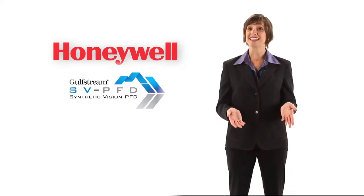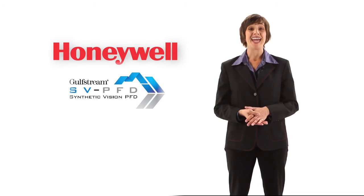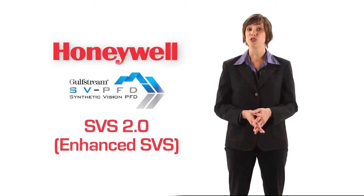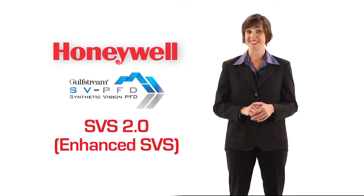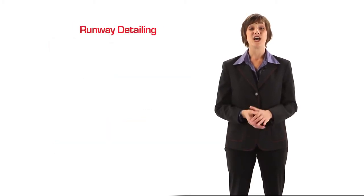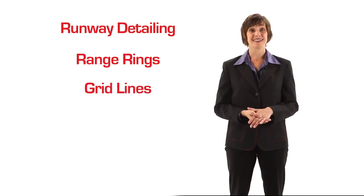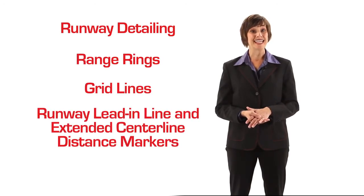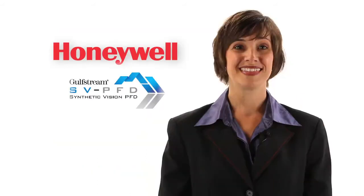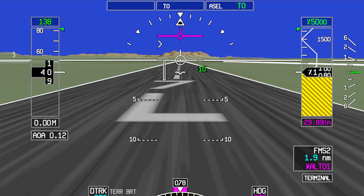In addition to the basic SVS features, such as the display of terrain data combined with primary flight and navigation data, aircraft equipped with SVS 2.0 or Enhanced SVS provide the following additional synthetic vision features: runway detailing, range rings, grid lines, runway lead-in line and extended centerline distance markers, and the enhanced HSI. Let's review some of the new features contained in SVS 2.0.